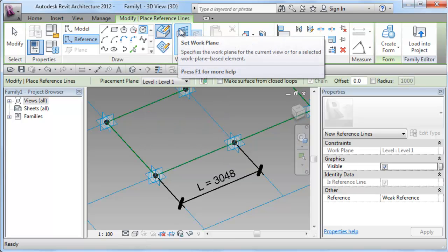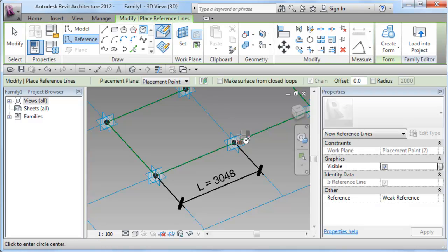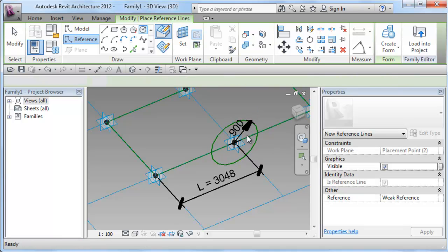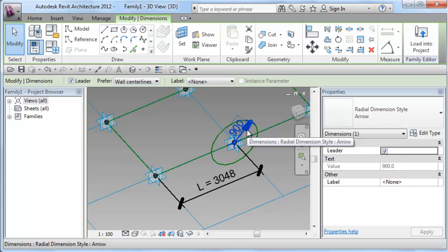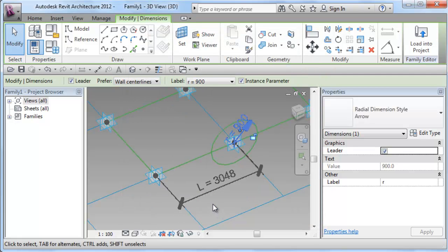you've seen in the earlier image, and now we'll just set the reference plane of that point and create our circle, just any dimension. I haven't worked out any particular dimensions for this, so we'll just turn the radius into a parametric value. I'll just call it R for radius for the time being. It's not really critical whether it's a type or instance, but I'll just keep going with instances. Generally that's my practice of creating these elements.